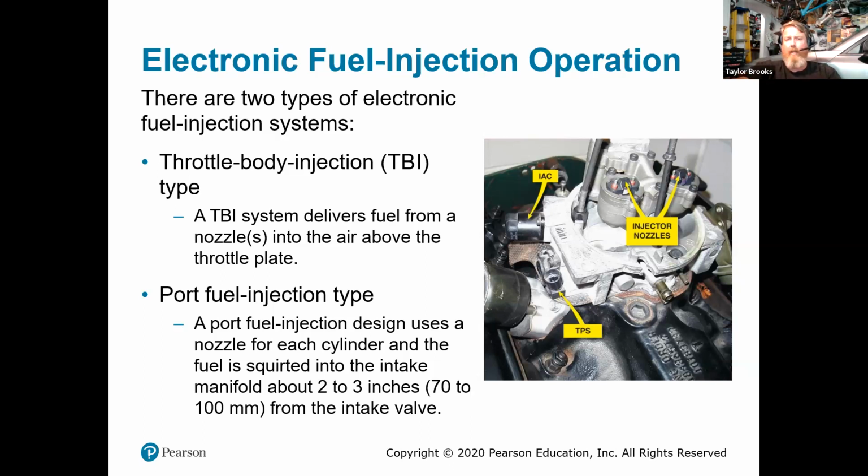There are the spray nozzle injectors that spray above the throttle blades. This is very typical of what you see right here for the GM TBIs. These are dumb reliable. I've installed these, I shouldn't even say aftermarket, as a different brand style of fuel injection on a couple vehicles, and they're really, really reliable in how they operate and function.